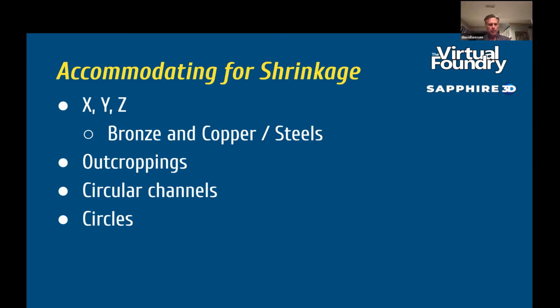Yeah, and I also think the size of the internal channel can make a difference as well. Some people have approached us with really small channels, and unfortunately I told them it's going to be difficult to measure internally what the change was. But for the ones that I did, those Autodesk ones, those were about a 1/4 inch diameter internal channel. There was definitely sagging in that channel, but we were able to address it with just some design tweaks.